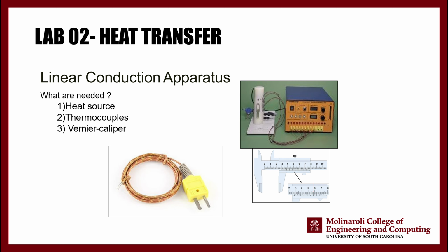Moving on, we are going to talk about transient heat conduction more in the next slides. But this is your equipment. This is what you're going to see. This is our power supply. This power supply is going to generate power, and it's going to heat up the top of this linear conduction device. At the bottom, we have cooling. This is connected to water, and some cooling is happening, which means that we are going to have a temperature distribution between these 2 points, right?